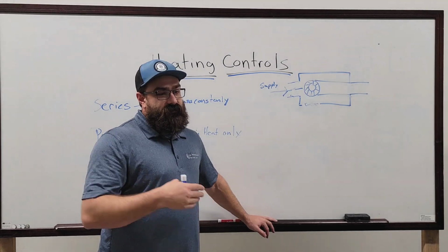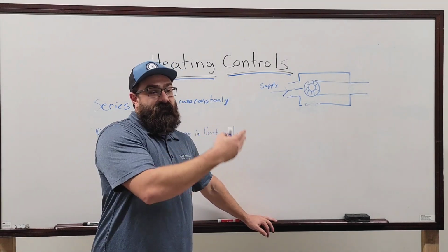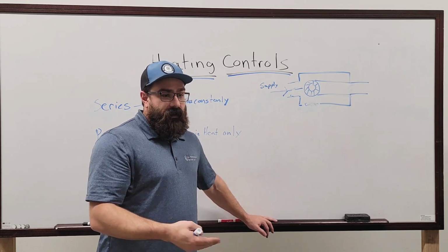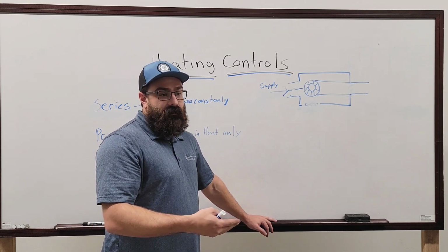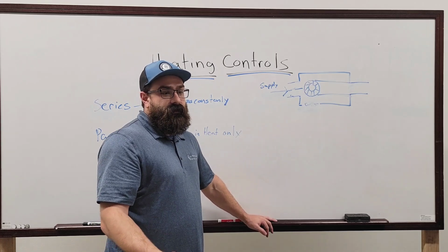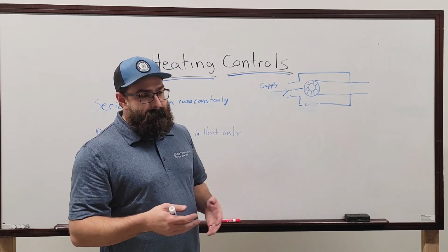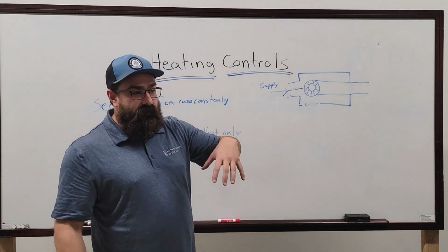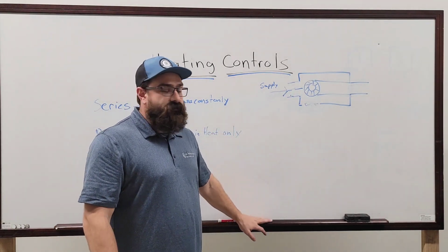Number 2, even though you have more motors per se in a building, they are fractional horsepower. So they actually use less energy than the big fan blowing air into them. You can take what would be a 40 horsepower air handler and drop it down to like a 20 when you have series boxes, because you don't have to supply as much pressure. And then you have fractional horsepower motors throughout the building, which draw almost no amperage.